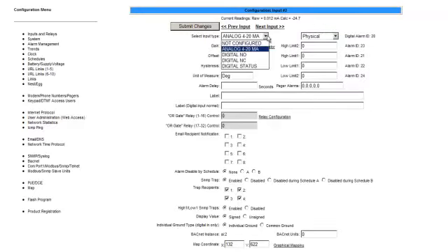So from the drop down, I'm going to select the proper digital type, the gain, offset, hysteresis, unit of measure. Our high and low triggers do not apply. An alarm delay could be used if needed. Pager alarms is for the internal modem dial out or SNPP paging.